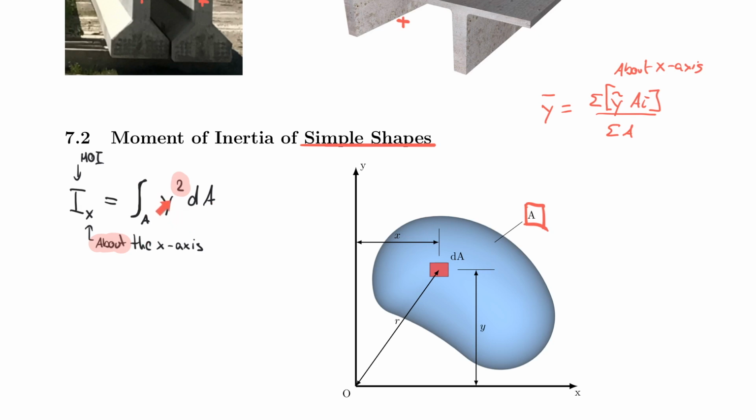So, what is it? It's the lever arm squared times the area, which also tells us something very important about this formula, and that is the units. I'll let you guess for a second what the unit will be. So the unit, of course, will be length times length times length times length. So we have a very strange unit here, which is actually length to the power of 4. And so this must always be true. It must always be length to the power of 4 because you have a lever arm that is squared times an area. And that's how we quantify the moment of inertia.